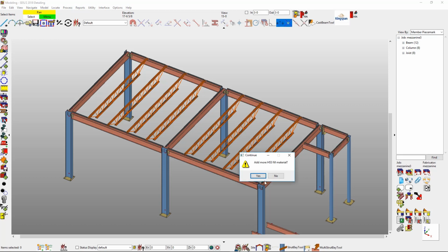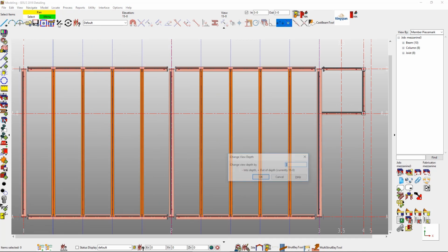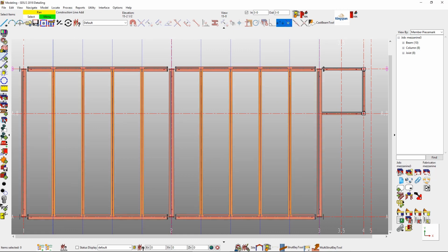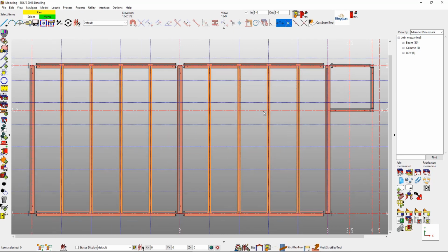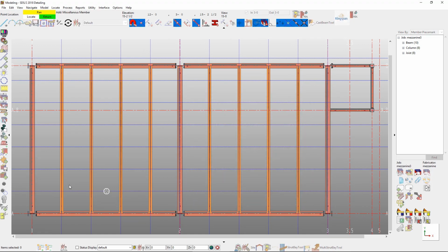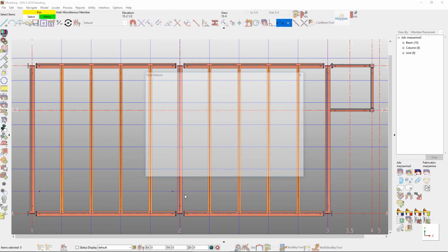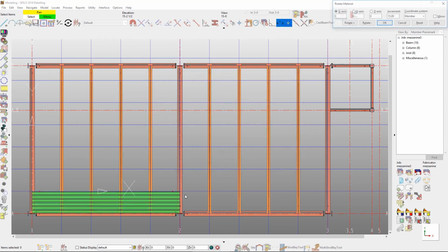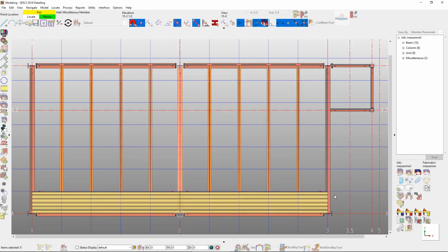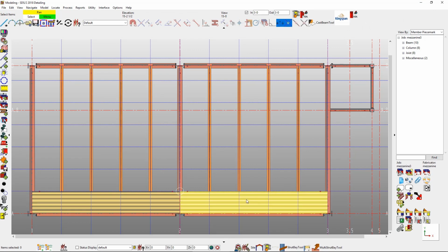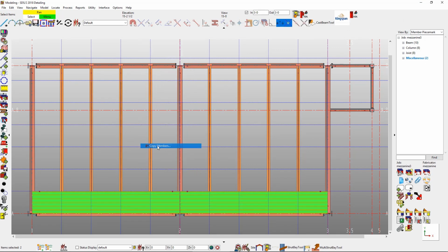A completed SDS2 model will include all the material that's located on site. So buyout items such as decking, grating, or plate will need to be defined within the fields. In this case, you'll want to know who your decking manufacturer is so you can define the number of ribs, depth, and thickness in the window. Once you've established that, then laying the decking out in the structure becomes very simple. You just pick the start and end points and then populate the fields needed from your manufacturer.